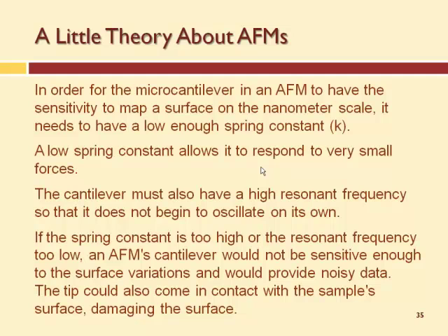Cantilevers must also have a high resonant frequency so that it doesn't begin to oscillate on its own. So you've got to make them flexible but kind of stiff at the same time. If the spring constant's too high or the resonant frequency is too low, the atomic force microscope cantilever wouldn't be sensitive enough.